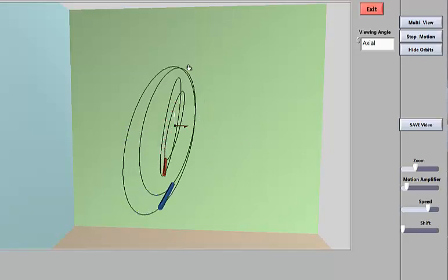And this just goes to show that most machines don't really have a clear run-of-the-mill 100% imbalance or 100% misalignment. Usually it's kind of a mix between these two. So in this case, the blue one is probably a little bit more imbalanced versus the red one is probably a little bit more misaligned.